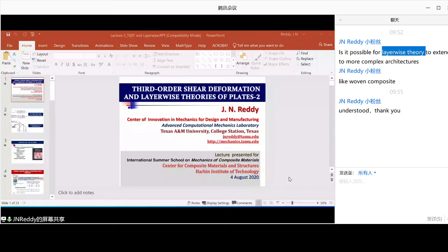That is not going to be different here. You still need a criterion for when the node splits. That means the stress sigma zz exceeding some allowable value, and then the node splits into two, and there would be two displacements.